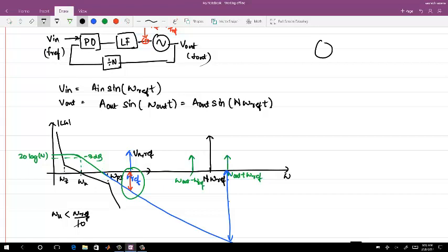So suppression you can get. Whatever delta you are injecting again depends on what the amplitude of V noise at the reference frequency is, which is exactly being applied to the VCO. So for a given VCO, V noise at the reference frequency gets translated to the output frequency with plus minus F out.